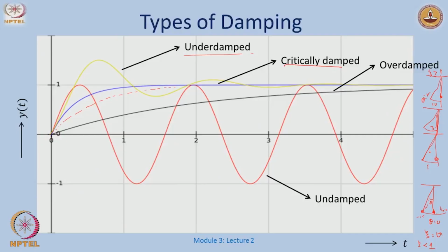If I want to design a lift or an elevator, and I want to go from, say, level 1 to level 2, I am lazy and do not want to walk, so I take the elevator and go up. I do not want my system to go halfway to the 3rd floor, come back here, and then do this. That would be very unpleasant. Even if, like you see on TV, Deepika Padukone is stuck with me, this will still be very unpleasant. Therefore, we design these systems to be critically damped or slightly overdamped, so that I just go here and slowly settle down.